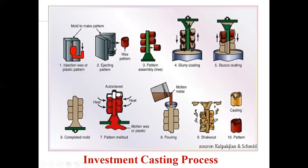With the help of this wax pattern that you produce out of an injection mold, we will make an assembly of those patterns. We'll dip it in a slurry, and once you have multiple coatings, we will heat that assembly so that the wax comes out and you have the shell. Then we'll pour the molten metal and shake it out so that you have the final casting. That shell will be shaken out either mechanically or manually, and you get the casting. So the casting exactly resembles the pattern.